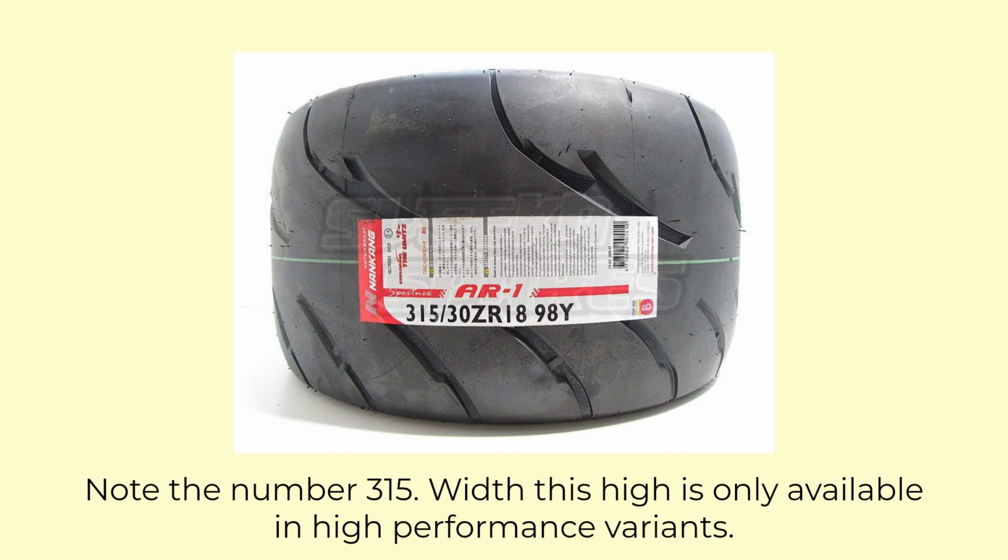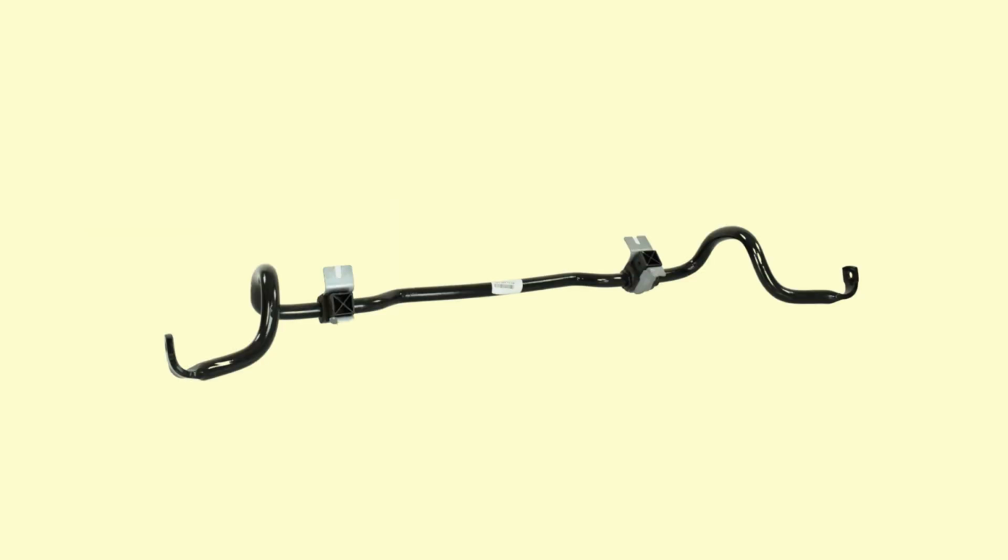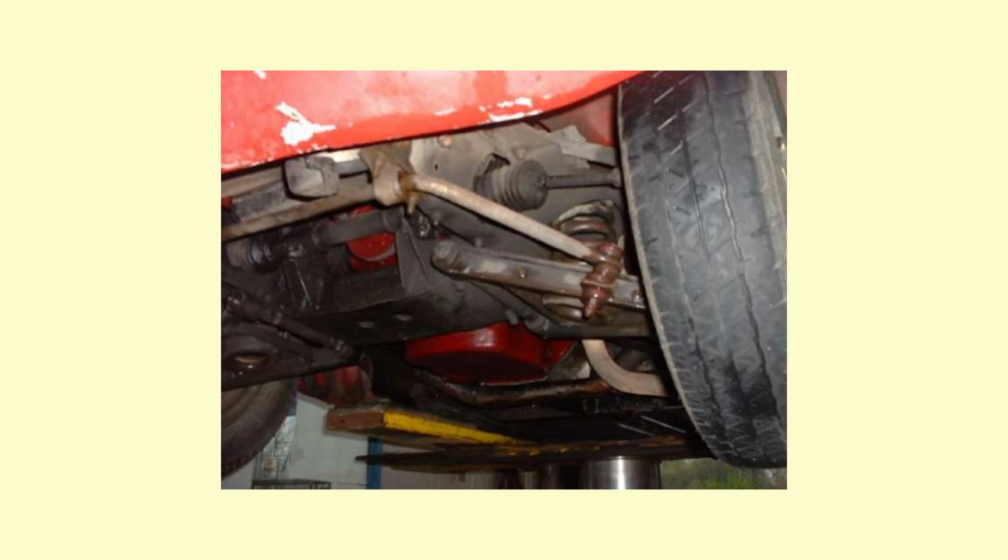One of the first mods we will suggest is fitting wider front tyres. As we know, a larger contact patch will mean the rubber can more easily deform. When understeer occurs in a situation where we have a front-heavy FR, such as a Mustang or a Corvette, this is a great modification to add, allowing improved grip and traction on the front tyres during cornering. A stiffer front anti-roll bar on the chassis underside can also be fitted to increase the roll stiffness of the front suspension, reducing the body roll. The lack of body roll keeps the front tyres more planted and stable on the road, yielding higher grip and traction, and allows us to dial in a better turn-in character.